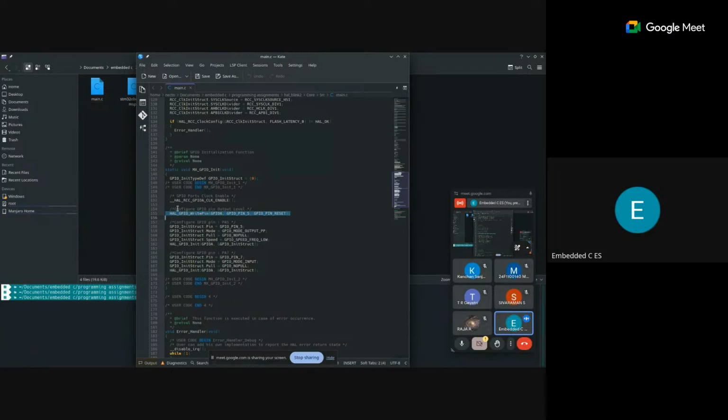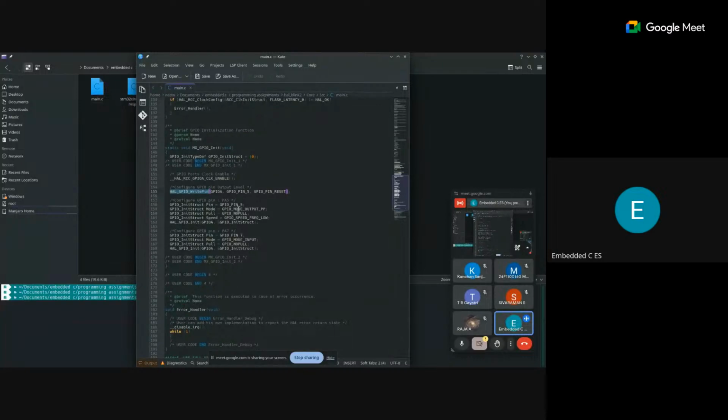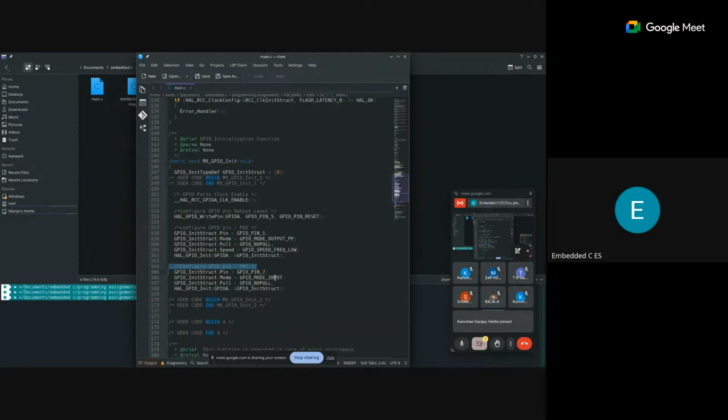Similarly, there is this HAL library, which is especially for programming the STM boards. Here, basically, these are the things that you configured, right? PA7 in input mode and so on. So CubeMX will generate all the configuration code that you need. You can do it visually instead of looking at the datasheet. STM provides an easy way for their boards to do things.